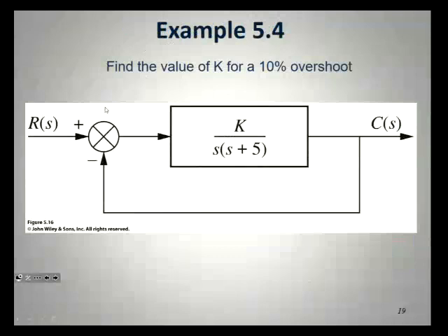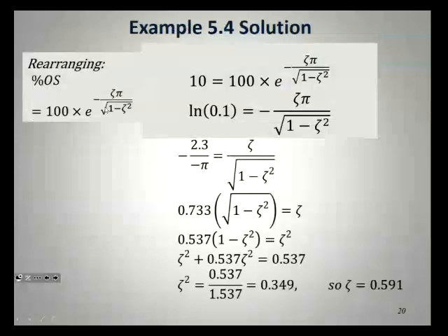Okay, and there's another example, find the value of K for a 10% overshoot. So this is a little bit similar to what you're doing in coursework 2, except you're using MATLAB to do that. So the way you would do it is, first of all, work out what was the zeta value using that equation that you've seen. This is just it rearranged. Actually, I wonder if...